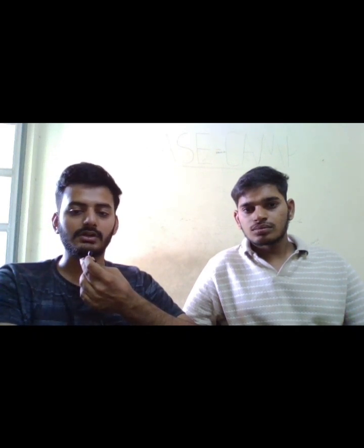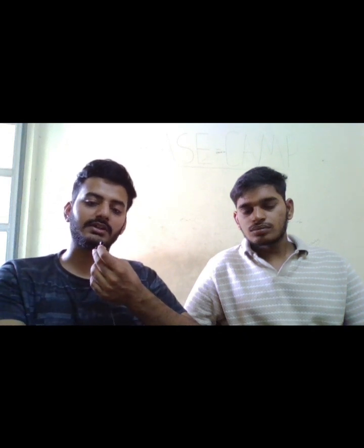Now Euler's equation, in which the Reynolds number is very much greater than 1, called inviscid flow. In that we have the dv by dt term, and also the del phi term. The term which will not be there and is neglected is the mu into del square v term.